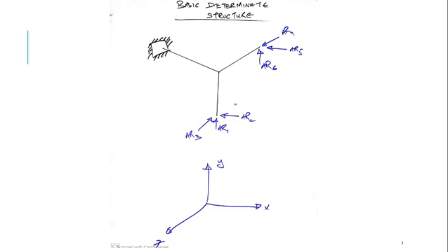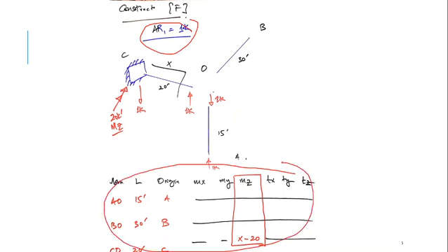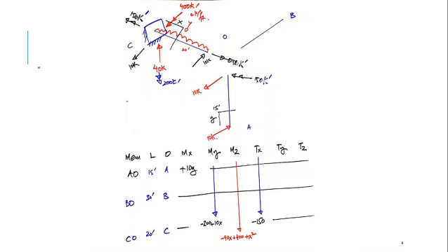Okay, next I've made the structure determinate by removing the two hinge supports, and all the 6 redundant actions have been identified. Applying the redundant actions one by one, I developed the moment table. By multiplying the respective values in the corresponding moment tables, I was able to generate the flexibility matrix. However, this step was missing, and it should come before the development of the flexibility matrix.